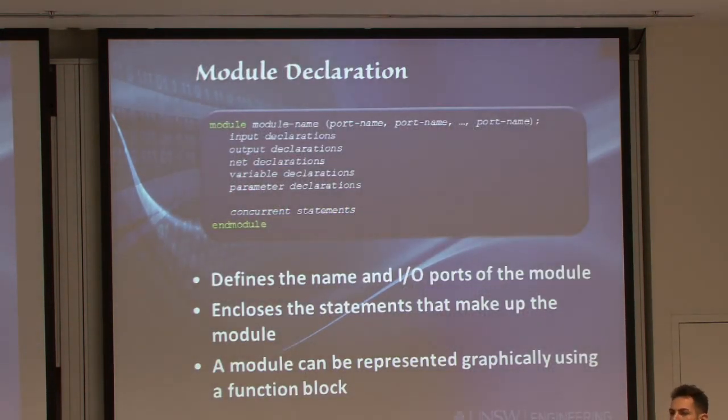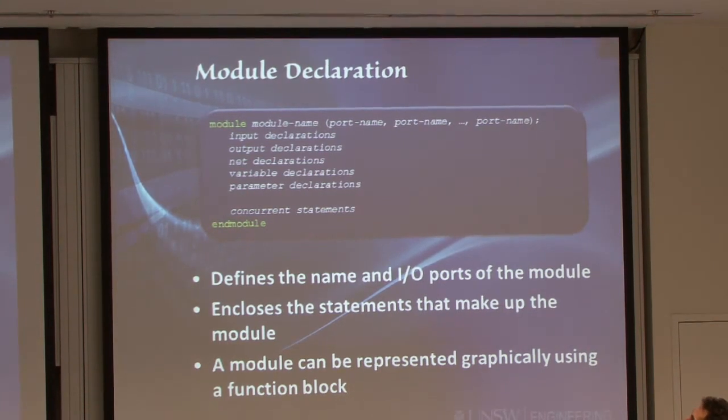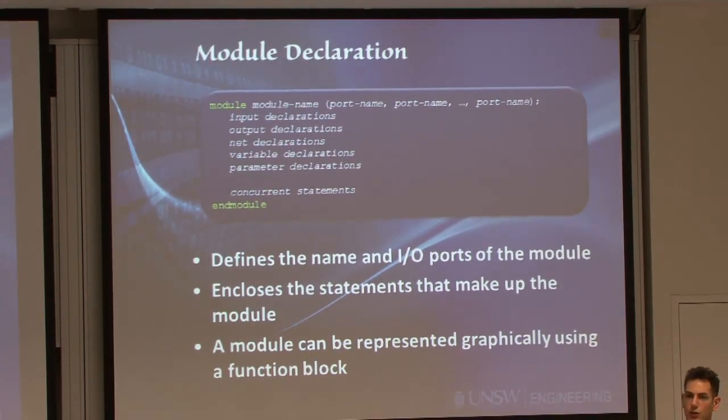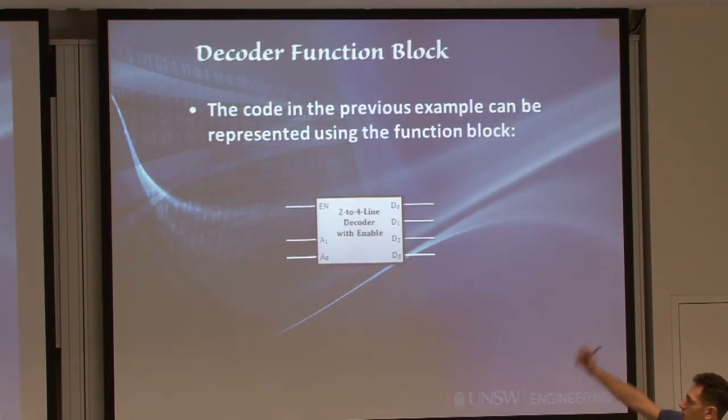Now, and this is where it gets interesting, the actual grammar. Every Verilog code starts with a module declaration. A module, if you want, is one of those black boxes, whatever is enclosed in it. And you can assign for every module the inputs, the outputs, and the functionality of this module.